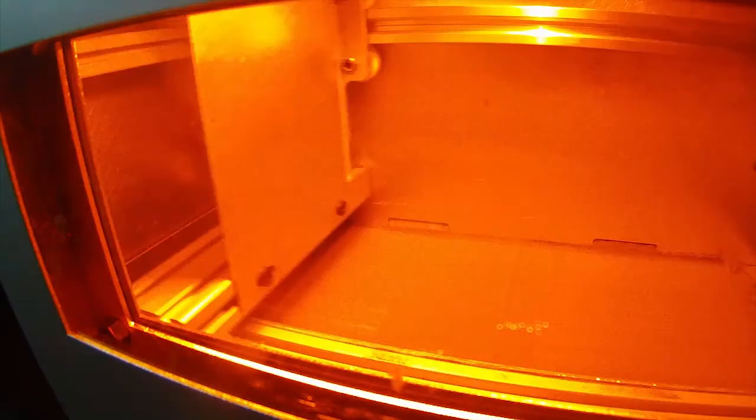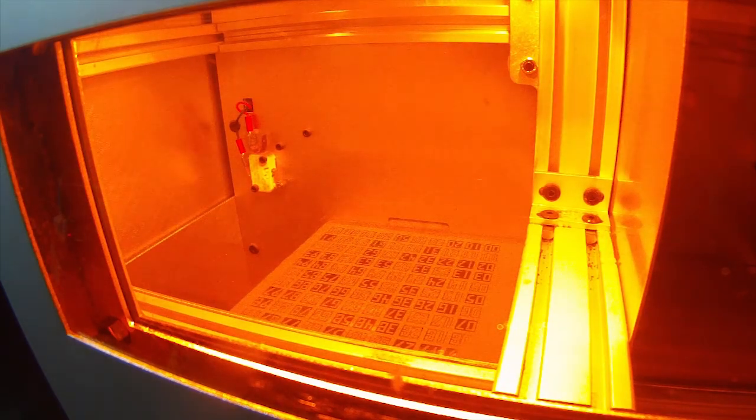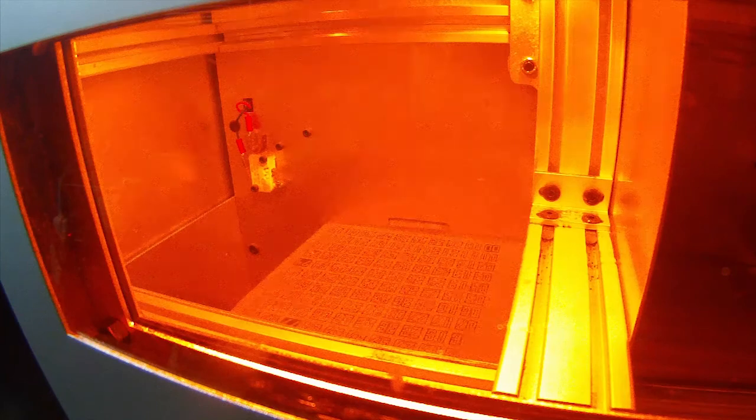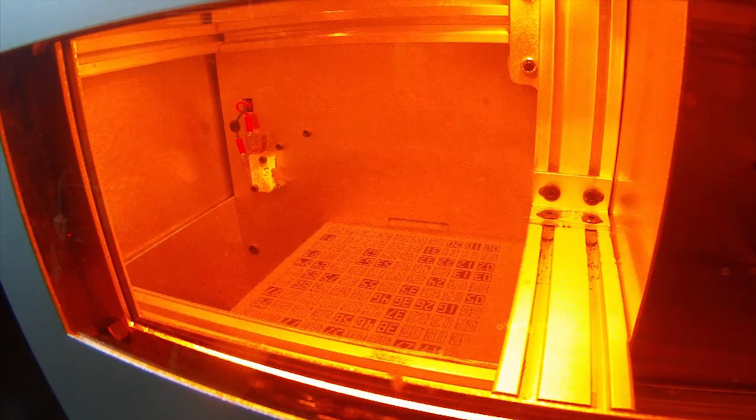I'm not having a lot of major issues, but I just want to know the full extent of what I can do. The other good thing about doing this grid is, as you can see, it's starting to populate the grid right now, it allows you to adjust the temperatures in real time and see where you're getting curling. In this first round, I started it with 172.2 degrees with a laser speed of 550.